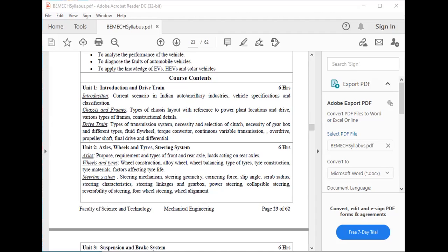The next is the clutch cable mechanism. It uses a steel cable inside a flexible housing to transfer the pedal movement to the clutch fork. The cable is usually fastened to the upper end of the clutch pedal, with the other end of the cable connecting to the clutch fork. The cable housing is mounted in a stationary position. This allows the cable to slide inside the housing whenever the clutch pedal is moved. One end of the clutch cable housing has a threaded sleeve for the clutch adjustment.